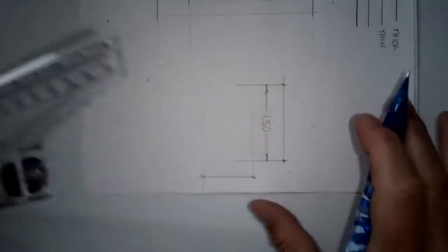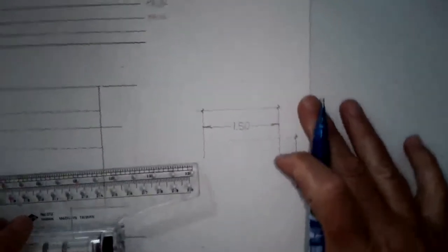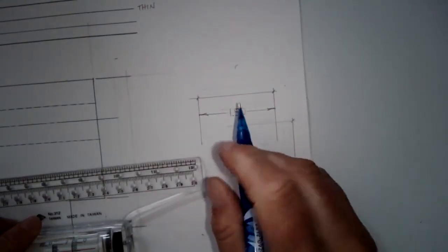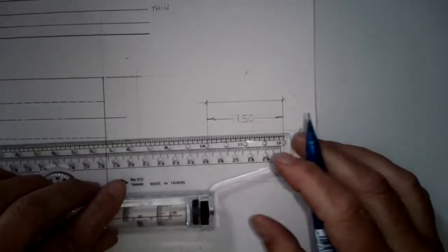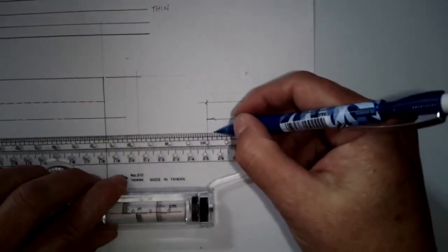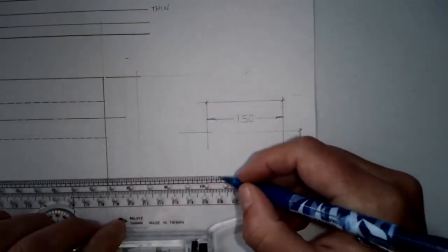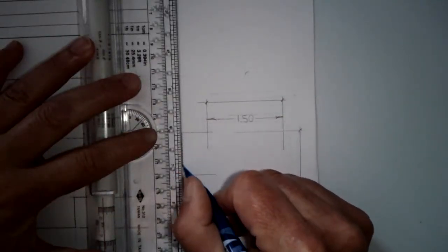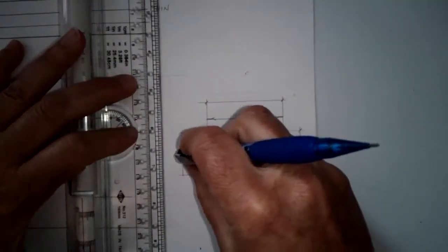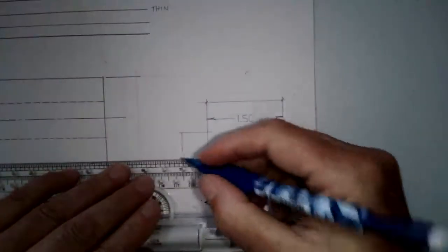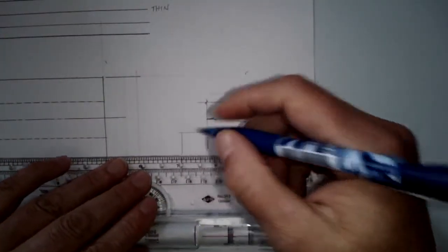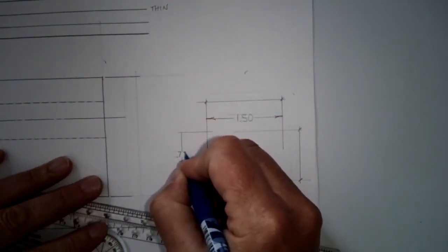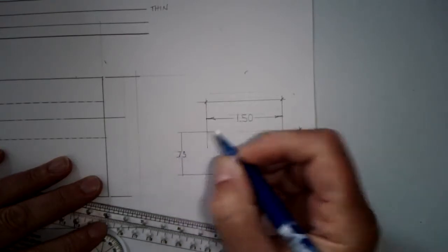Architectural dimensions follow the direction that the dimension is going in, whereas mechanical dimensions are always going to be in this horizontal position, even if you have a mechanical dimension going this way. Let's do a mechanical dimension on this side. You would erase and you would put your guidelines here this way and write in your dimension, making sure they hit the guidelines.